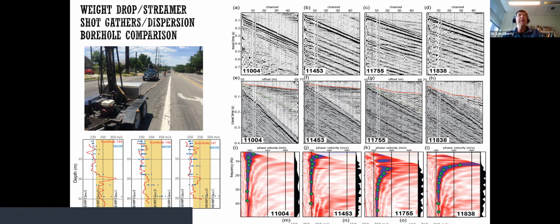And I'm going to talk about that again in a second when we talk about the effects of the asphalt on the Rayleigh wave response. But you can see the quality of the records. The one thing to emphasize here, as I mentioned, it's really hard to get body wave energy beneath the surface wave window. You can see in this particular example, as we were climbing an elevation, the water table was dropping. So our window between surface waves and the first arrival was actually quite small, and it becomes very difficult to actually pull reflectivity out. So I think in hindsight, these were 4.5 hertz phones. I probably would have collected data with higher frequency geophones to try to allow the body wave energy to get through the surface wave window.